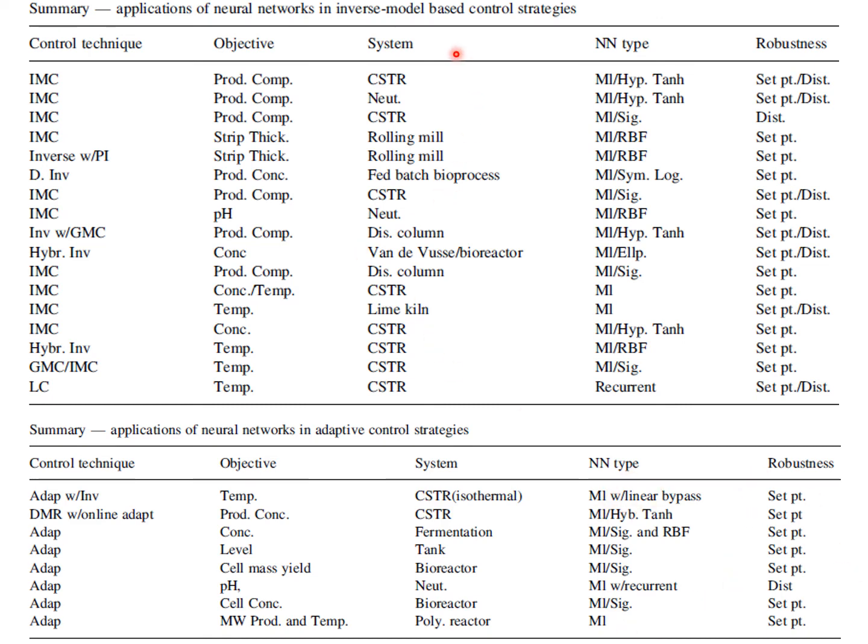As you can see, most of these systems are difficult to model using first principle. Because if first principle seems linear and easy to model, then there's no issue of using PID or conventional methods. But for systems that are difficult to model, highly nonlinear systems, this is where you use AI and advanced control methods to take advantage of their ability to model nonlinear mapping.